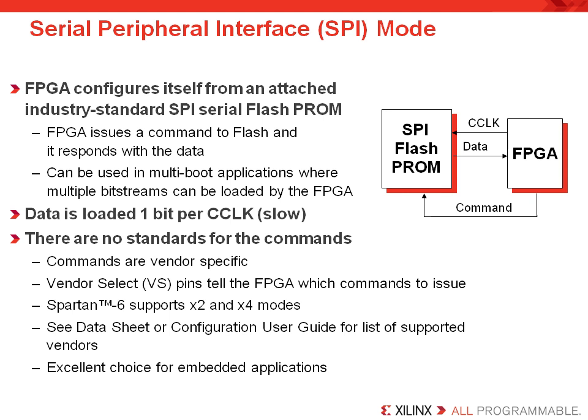However, if you're targeting Spartan 6, these signals are not needed since the first command code issued is always recognized. If you're planning on using Spartan 6, note that it also supports 2-bit and 4-bit data lines. The commands for SPI operations are vendor specific, therefore it is useful to make sure that you are using a supported SPI flash PROM. However, most devices will use the common commands supported.